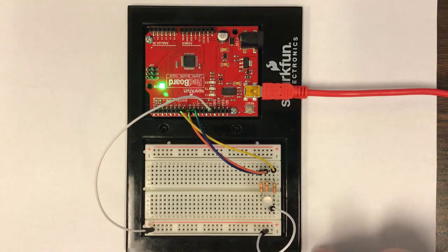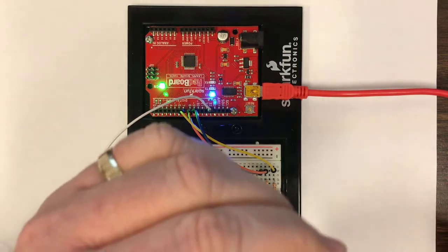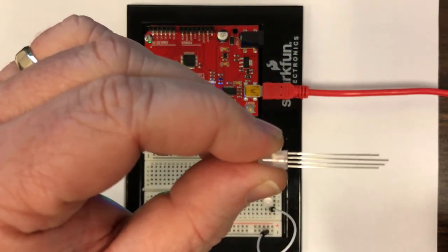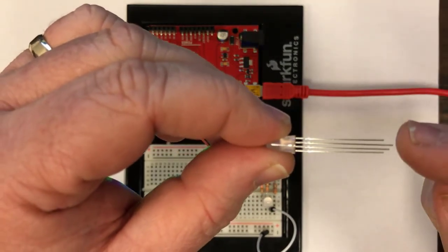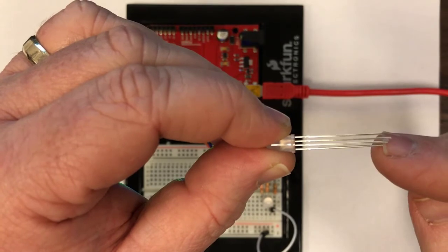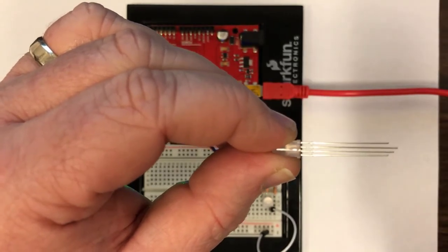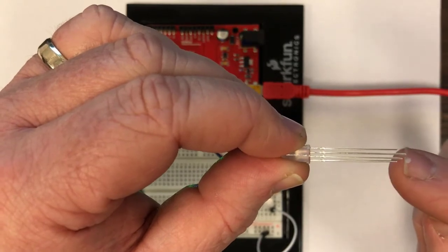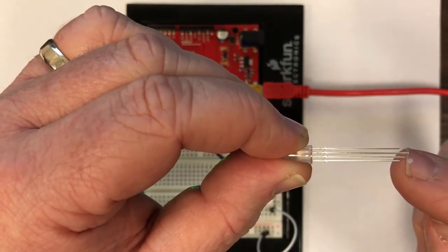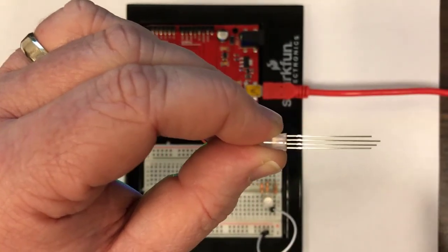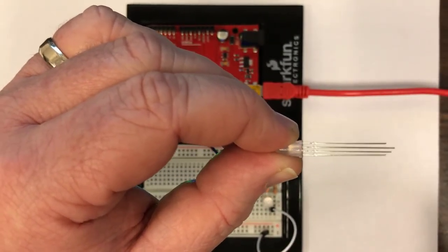So now that we've seen how to write the program to support the RGB LED, it's time for us to actually look at the circuit that we're going to use to implement it. Now here we can see this is an actual RGB LED, and for one thing you'll notice is that it has 4 terminals. Now one of those terminals is the longest one. That's the ground terminal, which is common to all 3 of the LEDs, and then there are 3 other terminals on here as well. The shortest one over here on the far side, that's the blue terminal. Next to the ground terminal, that's the green terminal, and then over here by itself is the red terminal. So you'll have those 4 terminals that you need to attach to the board.